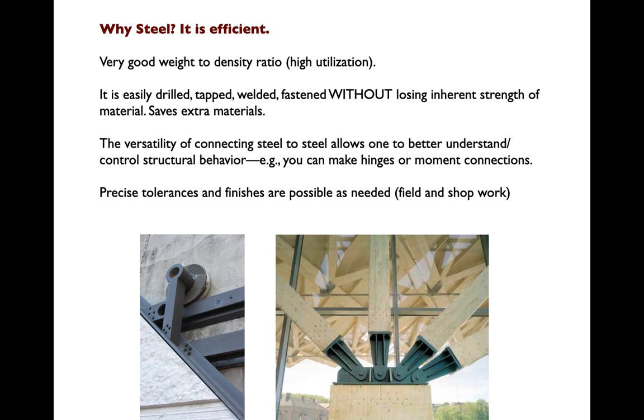Very difficult to do this in a lot of other materials because we don't have that precision engineering or that precision fabrication that can make a really, really tight pin connection. These can reliably transfer axial forces and they will distribute or get rid of the bending forces that those might bring into the base.